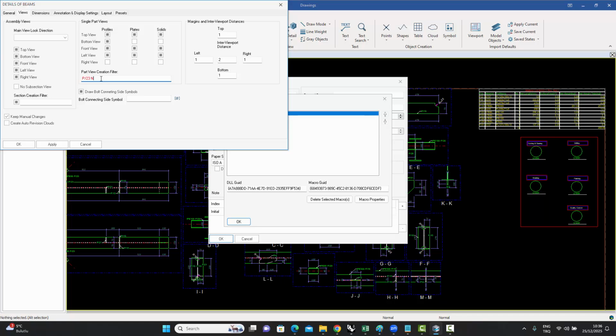But another option over here, other than the N, is that you can write things like F. F is for front, T is for top, B is for bottom, L is for left, and R is for right. And you can do it in any order you want. Instead of FTBLR, you can say LRBFT or whatever. The order is not important, only those letters are important.